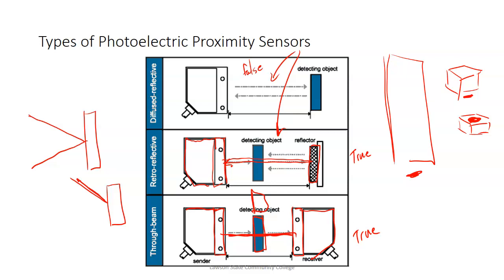And I'll give you all the color code, which is very, very important. So we have a standard color code out there too, that we can see what the power leads are. In fact, let's go. So plus DC is going to be brown. Minus DC is going to be blue.